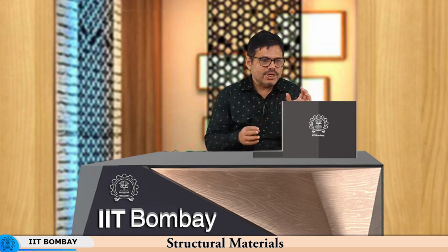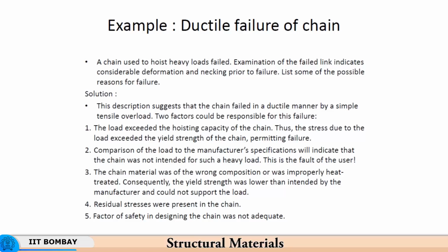That is what we call residual stresses, because when you bend the chain into the round shape it was supposed to get, then if you leave the chain as it is, you will have a gap generated between its two ends. So, you have a chain like this, you have brought these two ends together, and then after you release the load, there is a gap created between the two ends. So, what you do is you press this together and then you weld it. You apply weld here, or you might also use solid state welding processes.